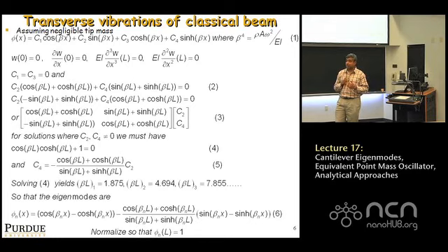And so this is how you find out what all the natural frequencies of the beam are. Okay? By simply solving equation 4 for beta values. If you go into MATLAB or Mathematica, you'll find that you'll get many beta values. There's a lowest beta value which corresponds to the lowest frequency, then the second lowest, third lowest, and that keeps going on.